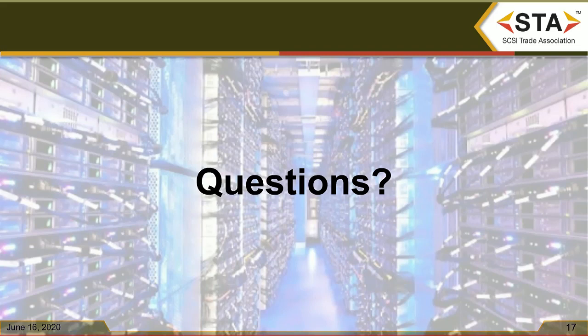And I think the last one, to achieve an 18-inch trace on backplane with a 6-meter cable, what budget was assigned to the host adapter? In SAS, we don't assign particular budgets to particular parts of the subsystem. You'll find perhaps in the back of the SAS specification an example in the appendix. I think they call out, what if we had 4 dB loss in the disk drive and 2.5 to 3 dB loss on the host before we got to the cable. But those are just examples; they're not requirements.